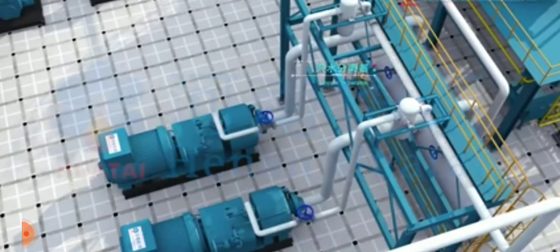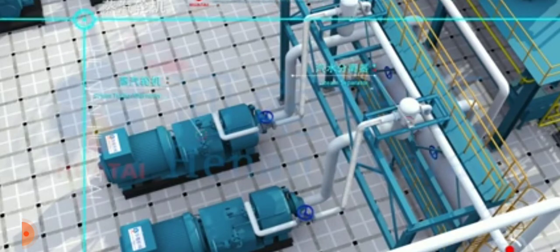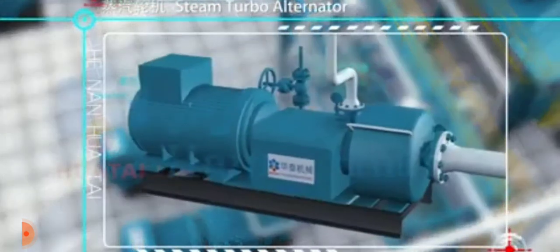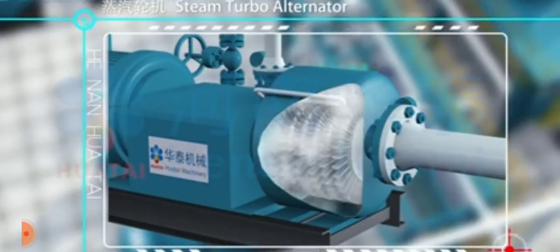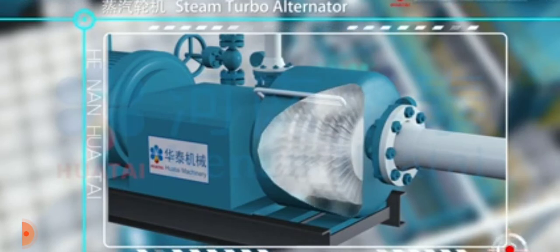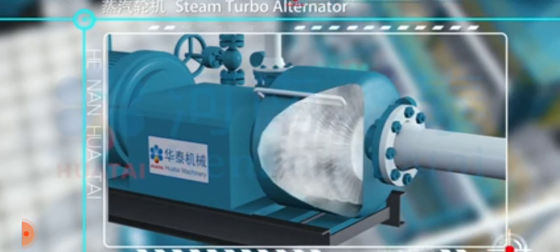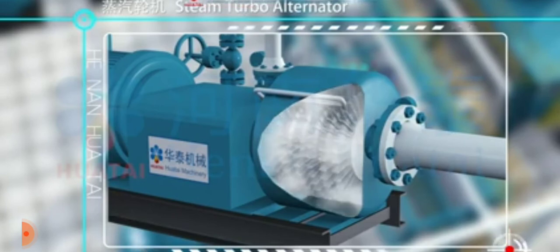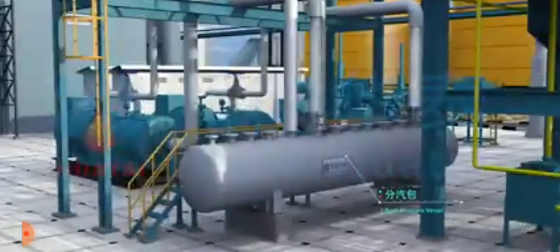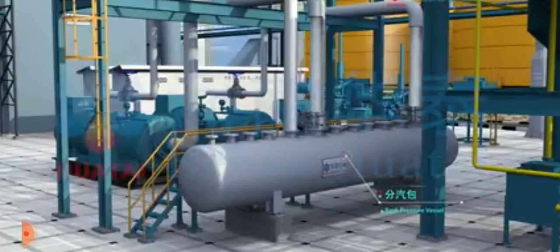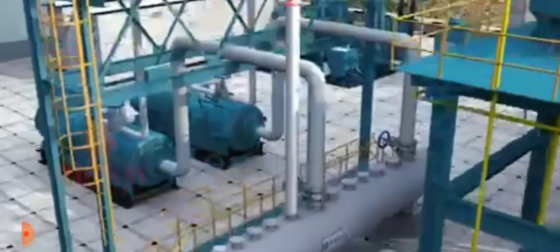Through the steam separator to reduce moisture of steam, it enters the steam turbo alternator. Under the action of steam with high pressure and temperature, the steam turbine generates high-speed mechanical rotation, converting mechanical kinetic energy into electric energy through the electric generator for plant production and living power utility. After the turbo generator, the pressure and temperature of steam reduce and the steam is stored in the back pressure receiver.